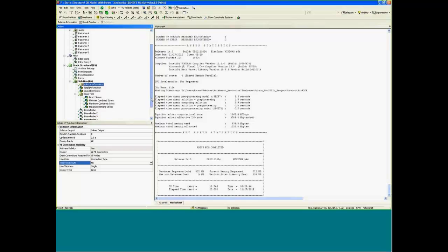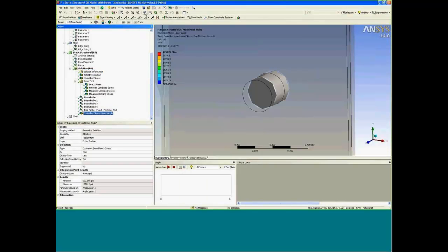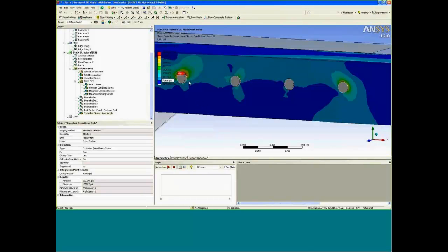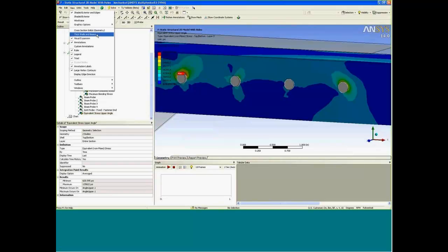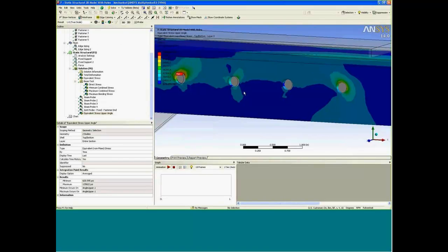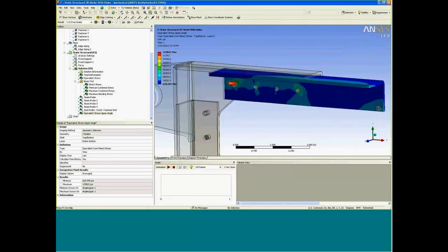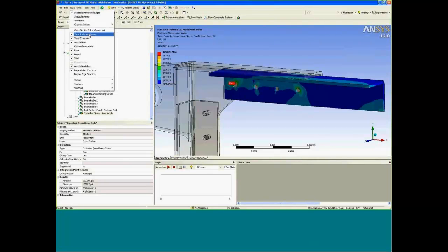Let's switch over now to looking at some stress review. You may be interested in post-processing stresses in individual components. So you can see in the connections, typically you have some stress peaking in the first fastener of the load or joint connection. If you do turn on your thick shells and beams for shell models, you can visualize stresses through the thickness, so it displays the shell through-thickness bending, and that's a visualization tool.